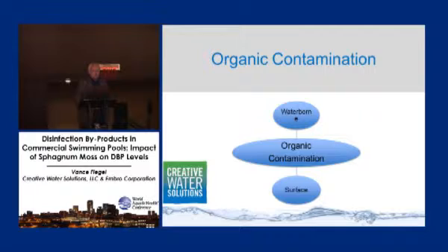Organic contamination is an important component because it's the reaction of the chlorine with organic contamination that creates these disinfection byproducts. I like to look at organic contamination as being in two phases. One is the waterborne organic compounds: the lotions, oils, sweat, perspiration, urine, things of that nature that are soluble in water.